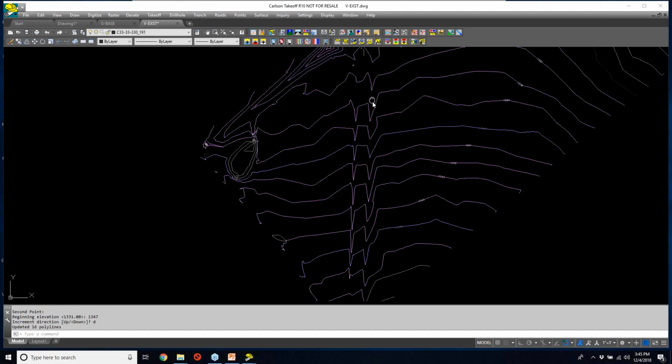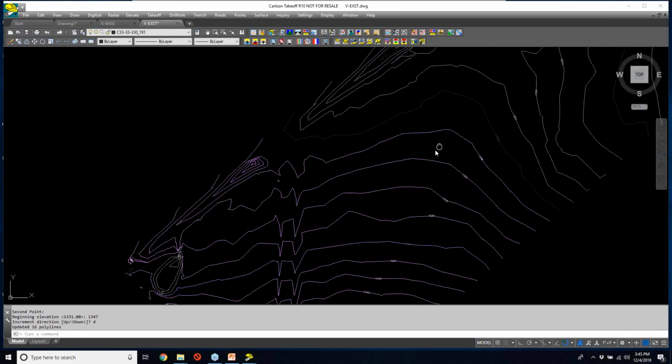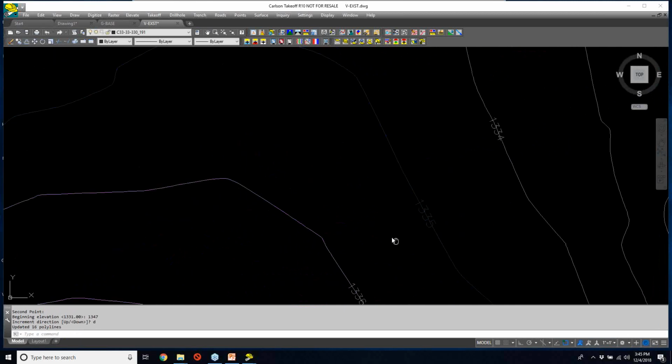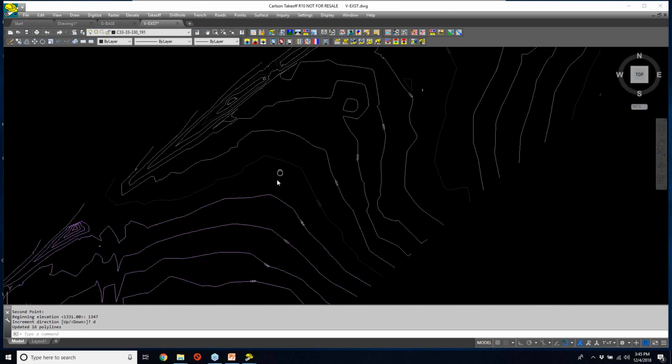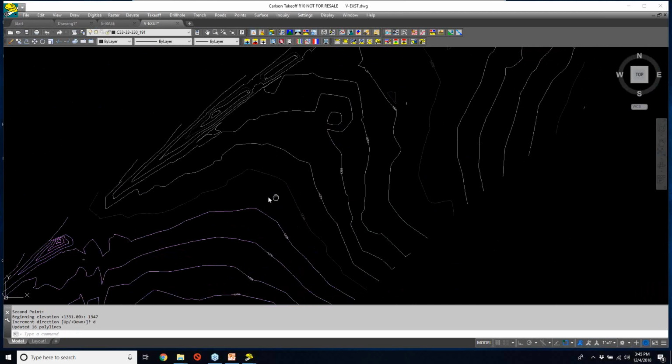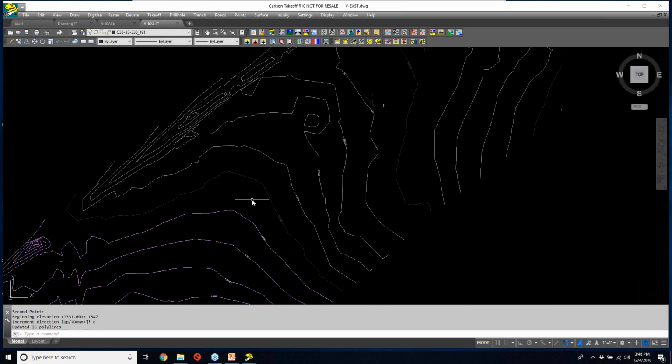All right, and as we go through now, it's just a matter of stepping through the rest of these in here. So again, I can say, all right, well, there's a 1335. The one thing we need to keep in mind as you are going through these is that you cannot change slope direction. So as I work through the next group, I would want to start here, and I can go all the way through that, even that little remnant right over here, making sure that I don't cross into anything that has a, that label, for example, is probably a polyline. So there's 1335 going downhill.